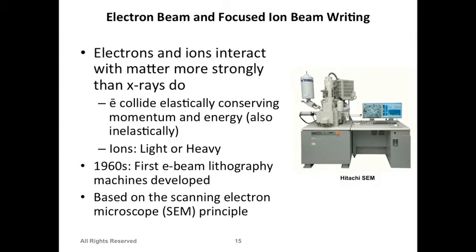Again, it will not be photoresist, it will be E-beam resist. Electrons shine on the surface, kick some electrons out, and transfer energy as heat and also momentum. Because of that heat and momentum transfer, the resist at the exposed areas disintegrates or breaks down into small chains which you can develop later on.